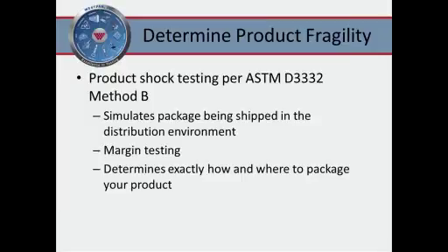And after you shock in every single orientation at one level, you'll do an evaluation. Evaluations usually consist of, one, a cosmetic evaluation, just to make sure your unit is not aesthetically damaged, and secondly, a functional evaluation. So you'll take your unit and run it through a series of diagnostics to make sure nothing adversely changed. At the end of one level, you would call it a pass if the unit you just shocked and a brand new unit have no difference at all. And if that's the case, you would bump up your test to the next level.